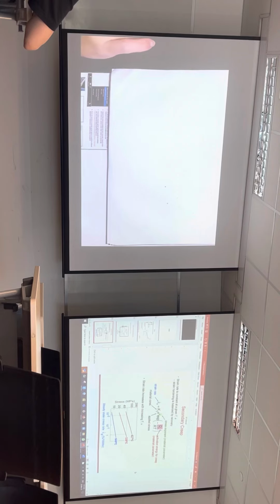The part where I also struggled is when I asked about precipitation hardening. How do you do precipitation hardening? You say precipitation heat treatment. Typically it is solution heat treatment, quench, age. Hardening is different; heat treatment is just the aging. Aging is fine with me, as long as you have done part of it, I'm okay. But I'm sharing with you the issues that I faced. I only remember that heat treatment for precipitation hardening only had aging, in order for precipitate to form. If you do that, I'm also okay.